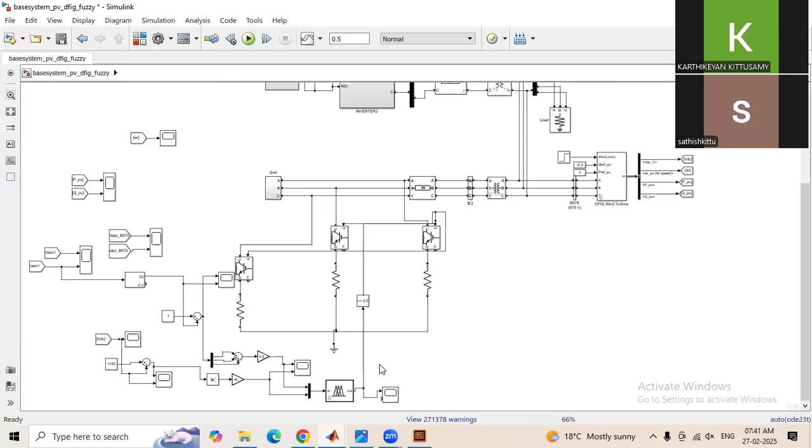The principle is that the crowbar protection offers the minimum resistance path when the fault has occurred, so that all the fault current will flow through the crowbar resistances and be passed to the ground, so that all the other components will be protected. This is the basic principle.